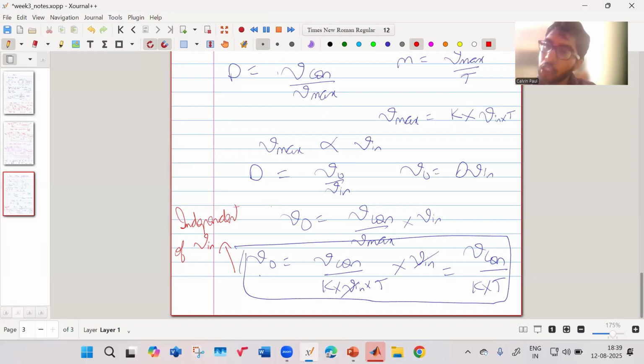That's an advanced bit of control for AC to DC converters, but we are currently focusing on DC to DC converters. This is known as input voltage feed forward. It has application in the case of buck converters. In boost and buck-boost converters, it's a bit difficult to implement because the expression becomes non-linear. It is not completely rejecting your input voltage.